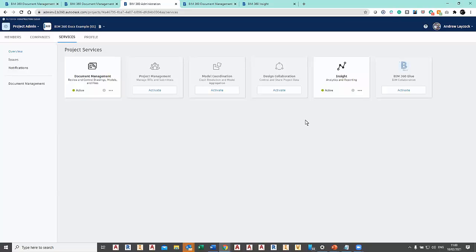It clashes model against model, so you can just go in and look at the two models and ask, what are the clashes? How do we deal with them? And it just happens. There's no messing about in Navisworks creating clash detection scenarios. The one thing it doesn't have at the moment, which I understand is being developed with the Navisworks team for the viewer, is non-true clashes, or soft clashes as you would call them. If you've got ductwork going through a building that's going to have 50 mil insulation around it, you can do that soft clash in Navis, which you can't do in lots of other things or in this. So you'd have to model the insulation. It's dead easy in things like Plant, because you just tell it the insulation is on and it does it, but in Revit we don't tend to do that. It's a really useful tool.